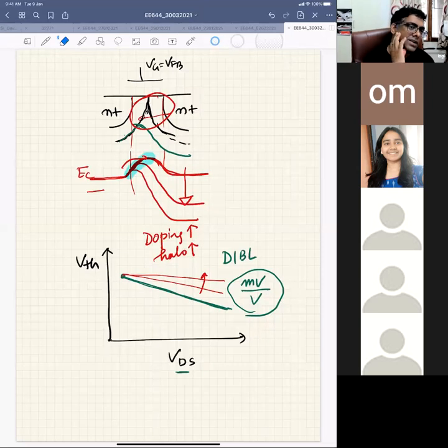If you want to avoid roll off, then choose a length where VTH versus L is flatter. I cannot really tell you at what length the short channel effects will come into the picture, but you could always delay them by different device design methods. To find out at which point they come, you just have to plot the device characteristic and see.